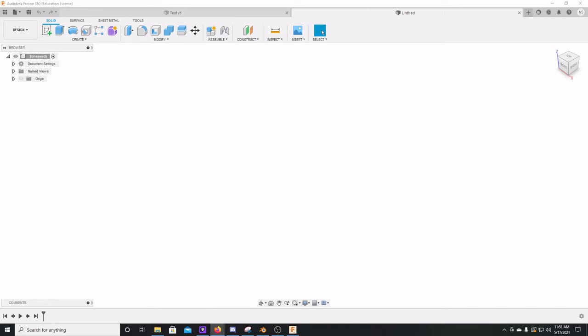Now 9 inches is about 228.6 millimeters. And I don't want to have the seam for the separator exact where the seam for the window is at. I think it'll weaken the integrity. So I'm going to make it a little bit off.